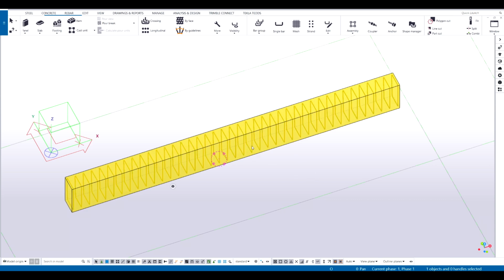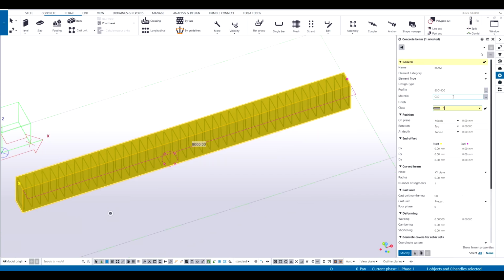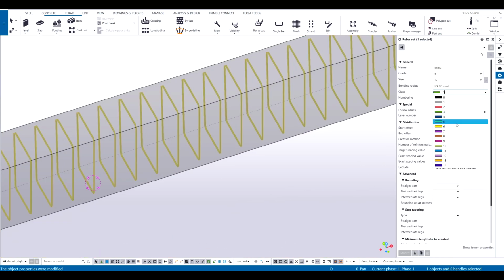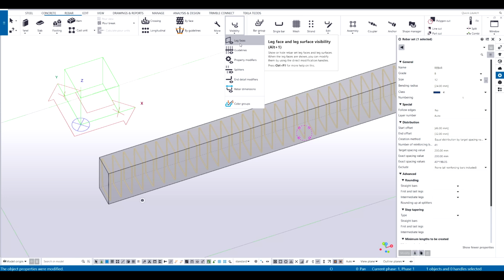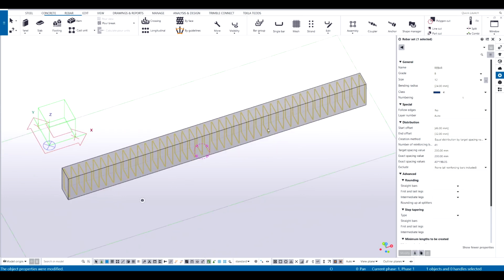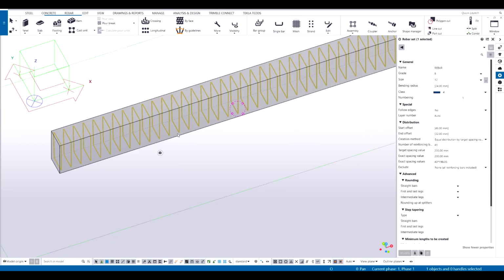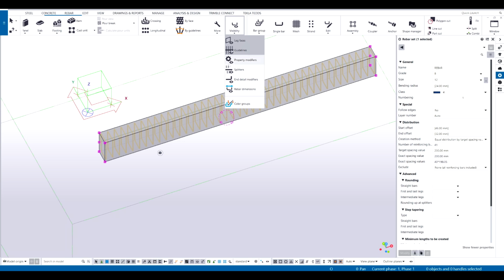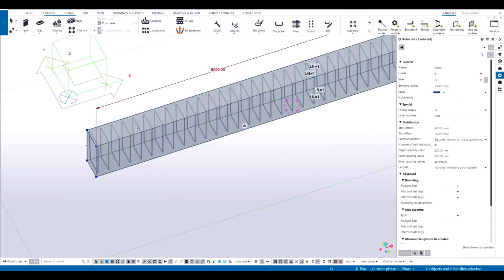Let's see what leg faces are. I'm gonna just make this maybe this thing. Let's give it a color that is maybe 1. And these ones, let's make them as 4, so that you know they are visible properly. Okay. You see this little button here? When this is turned off, no matter what you do, you can't see any of these visibility stuff. So it's kind of useless when this direct modification needs to be on. So let's click this. You see this grid line, this leg face appears.